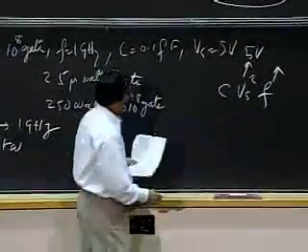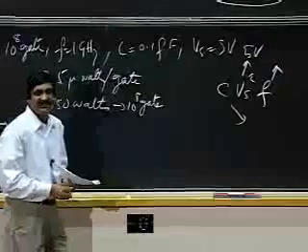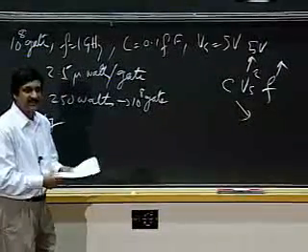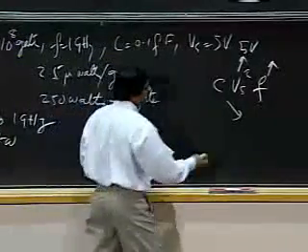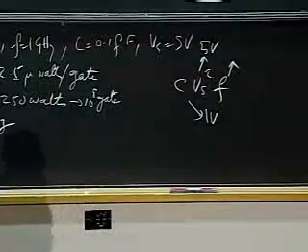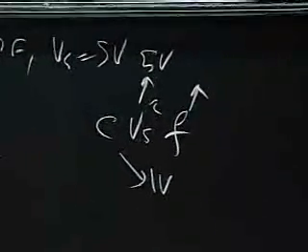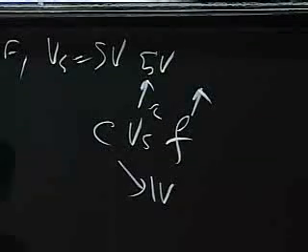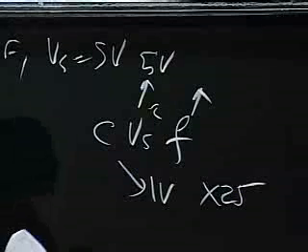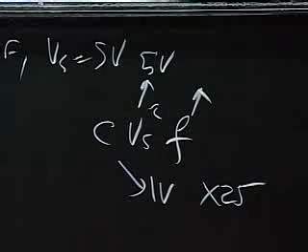It turns out that microprocessors, as newer and newer versions come out, run at lower and lower voltages. They invent technologies that use lower voltages and go from Vs of 5 volts to today's Vs on the order of 1.5 to 1 volt. The moment you do that, you get a 25x reduction in power. So going from 2.5 kilowatts, you would now come down to something on the order of 100 watts, which is much more reasonable.